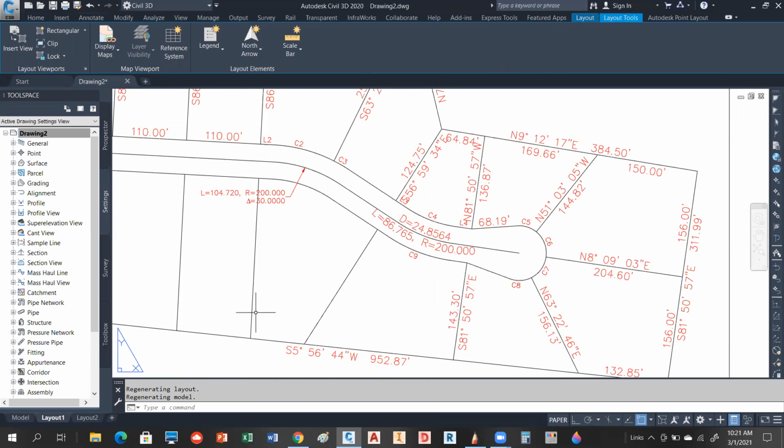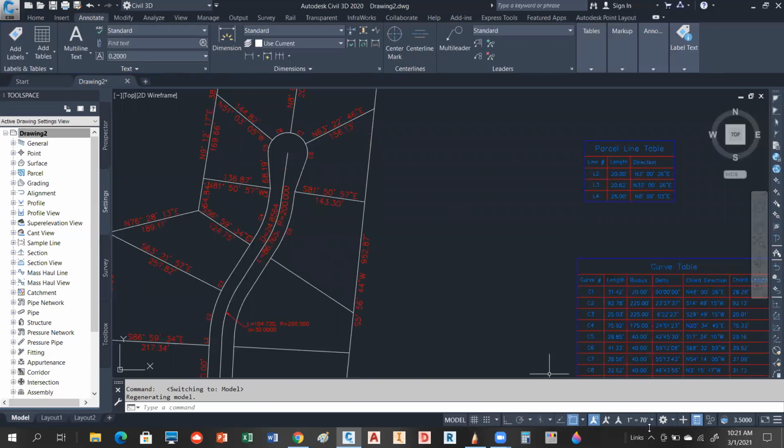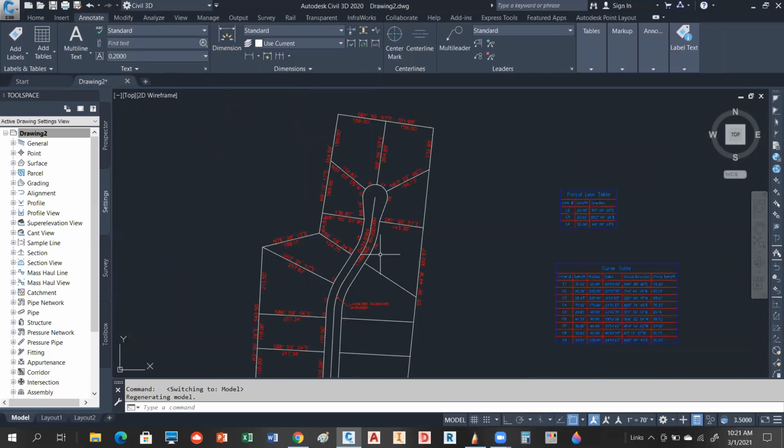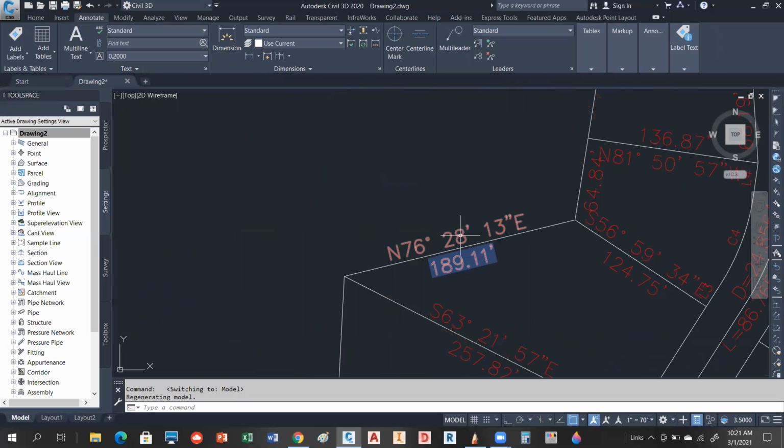So this really just shows you what it's going to look like at a 70 scale. However, this number does impact these guys, so you have to be really careful with your tables. Your tables act really strangely in paper space. They'll work, but if you want to have this at a 70 scale in paper space, then you want to make sure this is set to 70 before you go into paper space. Otherwise, they won't work right. Now, to answer your question, I think I answered it, but these are too big. That's the bottom line here.